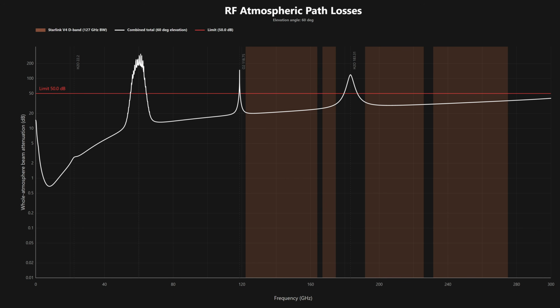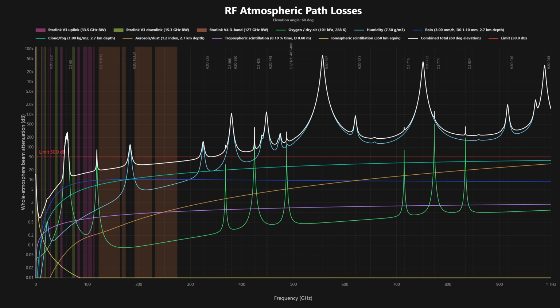backhaul capacity. The semiconductor industry has only recently advanced far enough to create efficient amplifiers and other electronics for millimeter wave RF. So that limits the amplifiers to operating at low power. However, because the antennas are such high gain, the link budget remains fairly good. At above 300 gigahertz, however, the microwave spectrum ends and the far infrared range begins, and we do not yet have the technology to efficiently or economically use this bandwidth.